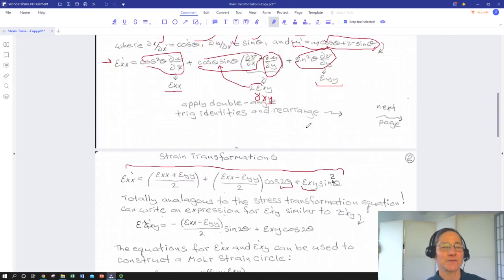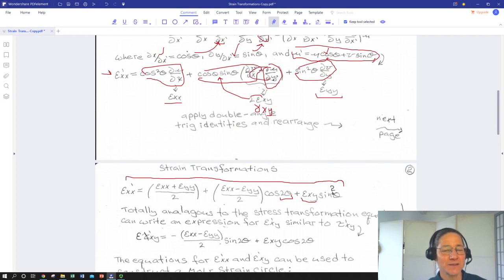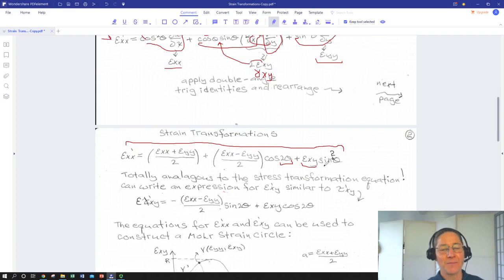So that's basically 1/2 of this, times sine of 2 times the rotation angle. So we're back to our 2 thetas. So from theta to 2 theta. So this is setting up to be very similar to our stress transformation relationship and setting up for a Mohr circle.